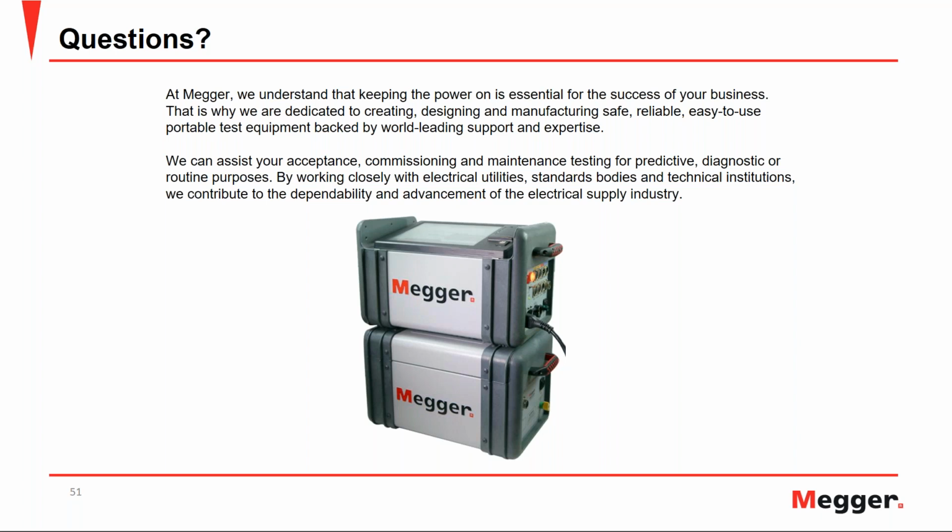Now let's talk about the leakage current. So leakage current is what is used to determine the power factor. It is used in the calculation of power factor. And a lot of times when people just look at the power factor value, and the power factor value is very, very small, it could be because the leakage current isn't flowing there, and that no flow or very little flow of leakage current could be because of a number of reasons. It could be instrument or operator error. It could be wrong connections.